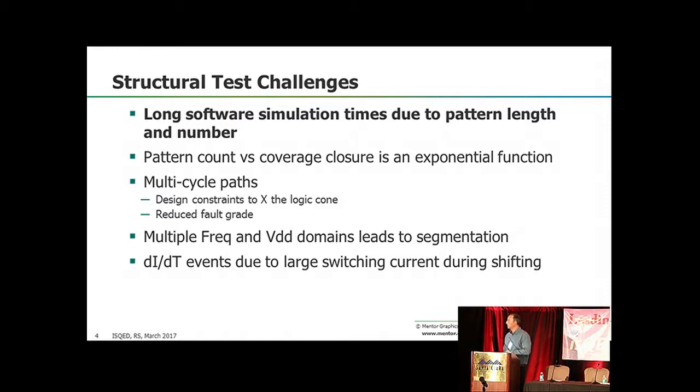So challenges. I've got that one bolded because that's going to be a recurring theme here. These patterns are very, very long. It can take days, weeks, and even months to run this stuff during traditional software simulation. You've got large numbers of patterns that you have to simulate. On top of that, in order to increase your fault coverage, you may go from a pattern set that initially started at 400 patterns with 98% fault coverage to over 4,000 patterns to pick up that one last 1% or so.